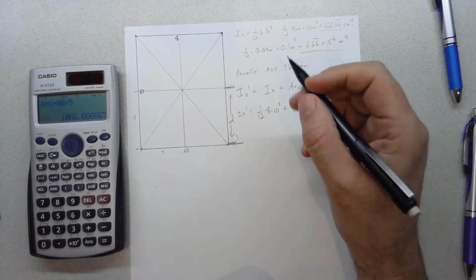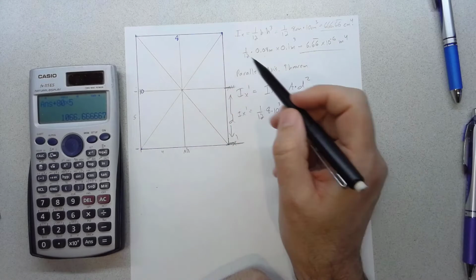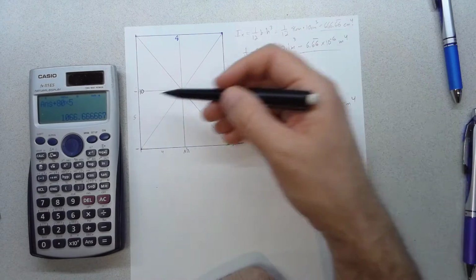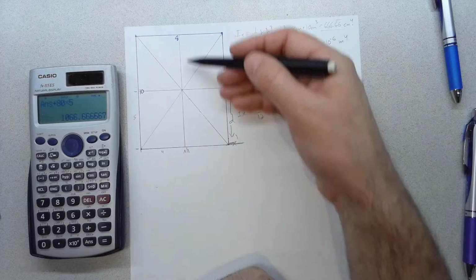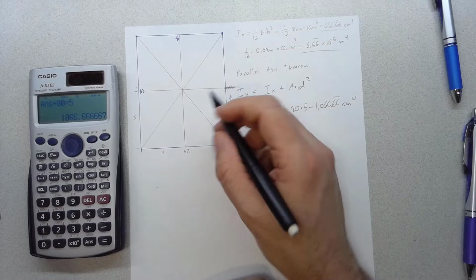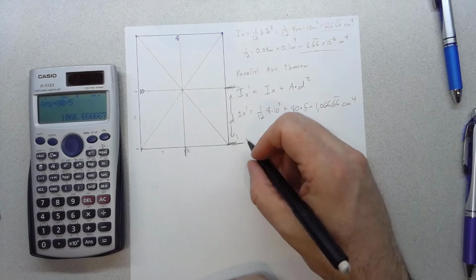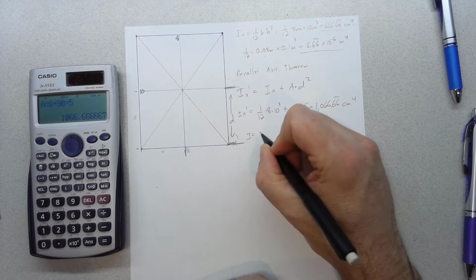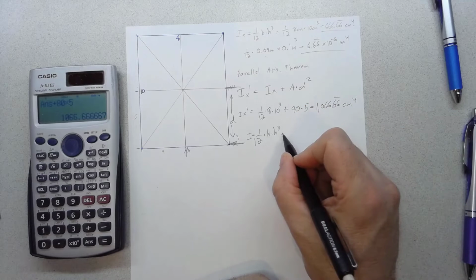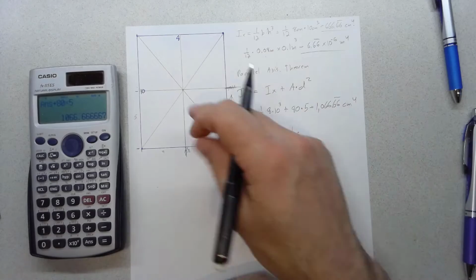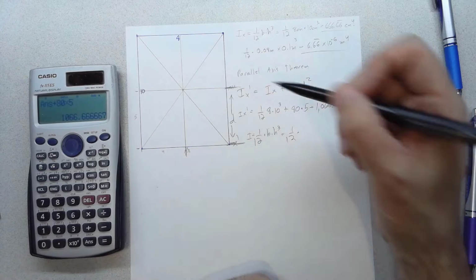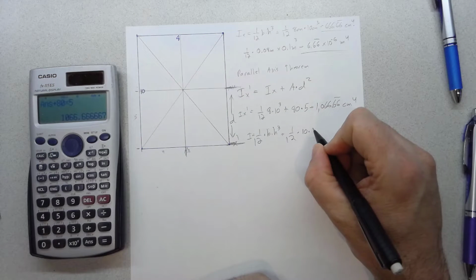And I guess actually before we go on and look at composite shapes, let's point out that this shape has different stiffnesses depending on whether we're bending about an axis parallel to x or an axis parallel to y. And so let's just plug in the numbers to that. If instead of finding out I about this axis, we want to find out I about this axis, we can use the same equation. It's going to be I is equal to 1/12 bh cubed. It's just now b and h are swapped. So it's 1/12. And now our base, because remember the base is always the length parallel to the axis that you're bending about. So it's 1/12 times 10 times 8 cubed.